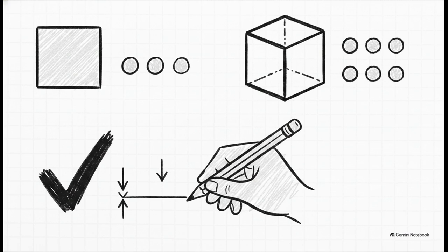Here is your ultimate cheat sheet summary for acing those final exams. For 2D problems, you have a maximum of 3 equations and 3 unknowns. For 3D problems, it's 6 equations and 6 unknowns. And the golden rule: always begin by drawing an accurate free body diagram. If you get the visual representation right, the math naturally follows.